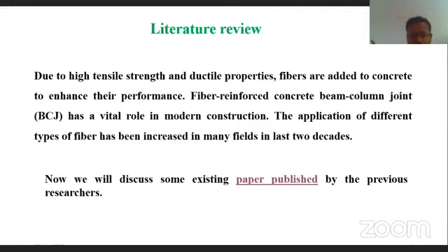in the construction sector. Further, we can see Ridwan Rahman Samir et al. They have also used carbon fiber to minimize the damage and also the deterioration of the concrete. It is published in an ASCE journal, and we can see the epoxy coated steel bar enhanced joint shear strength, ductility, dissipated hysteretic energy, and stiffness by 21%, 93%, 54%, and 30% respectively. So we can see further.